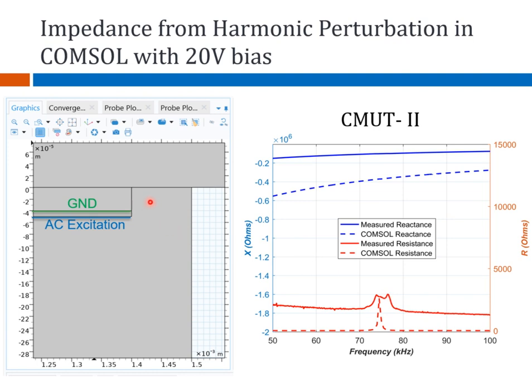So if you do not include the dampings in the COMSOL model, you don't get those baselines. And that impedance has to go into the circuit models; you have to include that loss in order to match what is being measured and explain what is going on. So the physical explanation is the damping of those vibrations in the glass.